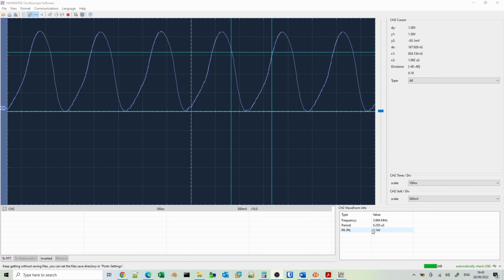So this will be explaining one reason why the duty cycle picked up in the logic analyzer will not be 50%, for example, because the logic analyzer, I have marked on here a line, this line here marks 1.58 volts, which is what the logic analyzer is treating as logic 1.